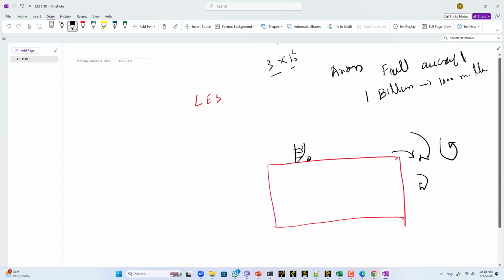I told you in the very first class that if the Reynolds number is 10 power 6, then the mesh size for LES would be almost 1 billion. And if you talk about DNS, that will be like 38,000 billion. Not possible for today's computers. But even with the latest technology, they employed 40 L40 GPUs, and they are very expensive.